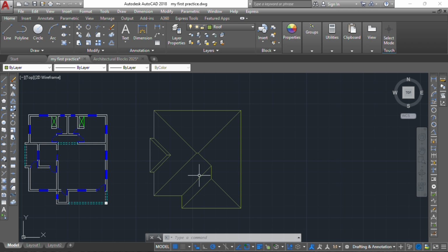So now we need to make each of these triangles, or this shape, we need to offset them to get the ridges and then our gutters. And for us to be able to do that, we need to turn each of these triangles to a bounded area. We need to make this triangle one. This side here, we need to make it one because it is our roof also that we'll be using for our elevations.